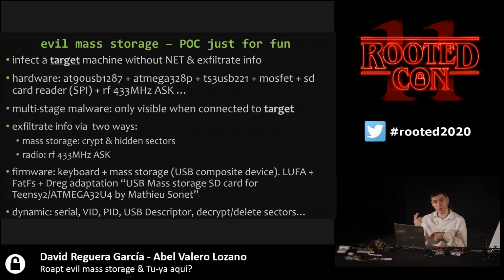only worked with old SD or SDHC cards. Everything was static. Then I got the FS for 8 bits, for when you want an embedded system. When you want to do things with the FAT system, you use that library that has been highly tested. Then I put everything together within the SD, and it doesn't really matter whether the SD is an old one or the new one, SDHC cards of 16 or 32 gigabytes. It is highly tested code, and I adapted everything for the CPU, and that was it.